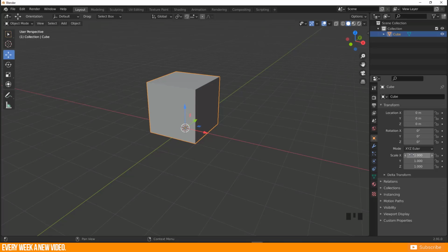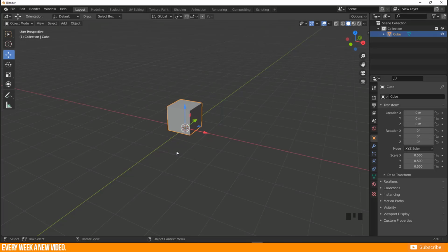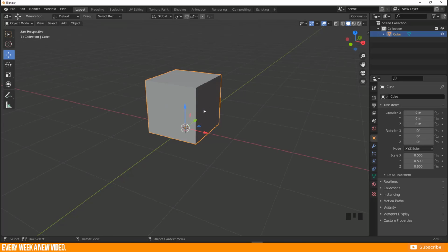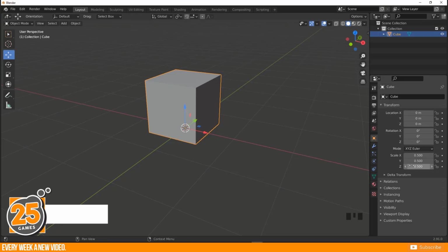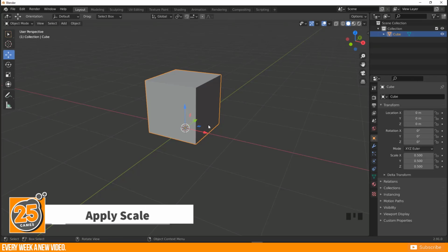So the thing we need to do is just click and drag the value from the X to the Z position, then you get this enter option and I press 0.5 and now my cube is half the size, so 1 was the actual size and 0.5 is 50% of this, and so we get 1 meter. And this is a better option to start because then I can enter the values very easily. And now our value is not 1 anymore, and I want to go back so that 1 meter is our starting position.